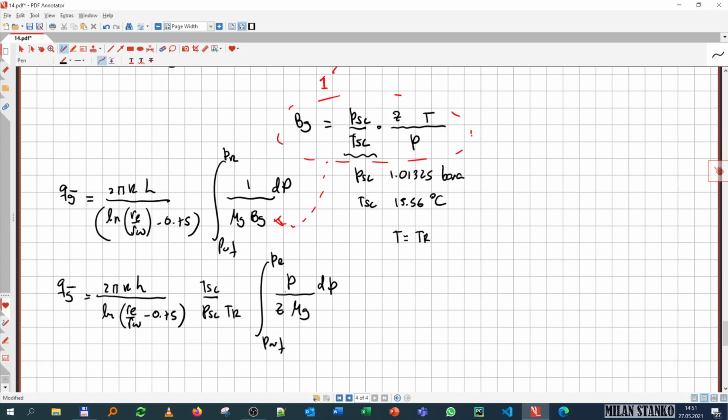So that's how our equation looks. You see that a lot of constants came out just simply because of the Bg. If we are defining the Bg with the Z, we can assume it's exactly a dry gas. So we can simply take all of this out of the equation and it becomes a constant that is going to contribute to the constant part of the IPR. But now our fluid related properties, we know exactly what they have inside: the P, the Z, and the viscosity of the gas.